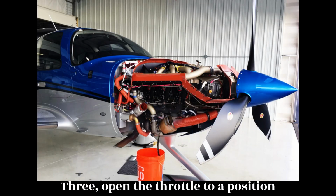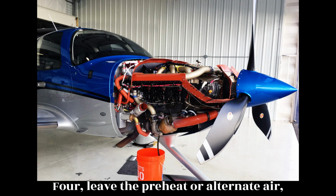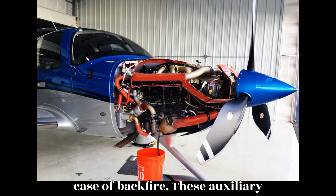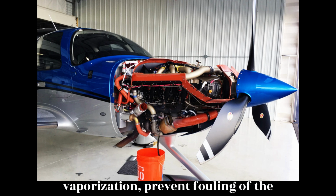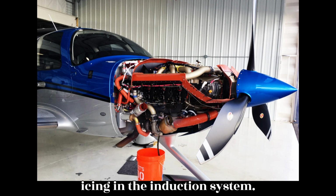3. Open the throttle to a position that provides 1000 to 1200 RPM, approximately 1/8 inch to 1/2 inch from the closed position. 4. Leave the preheat or alternate air, carburetor air, control in the cold position to prevent damage and fire in case of backfire. These auxiliary heating devices are used after the engine warms up. They improve fuel vaporization, prevent fouling of the spark plugs, ice formation, and eliminate icing in the induction system.